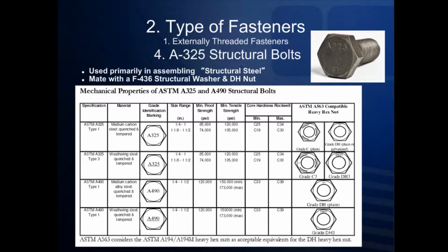The flat washers to be used for structural applications shall be ASTM F436. Therefore, standard USS pattern flat washers are unacceptable for structural steel applications. When looking at the mechanical properties of bolts, it appears that the ASTM A325 and the grade 5 hex cap screws are nearly identical. And also the A490s are nearly identical to the grade 8 hex cap screws.